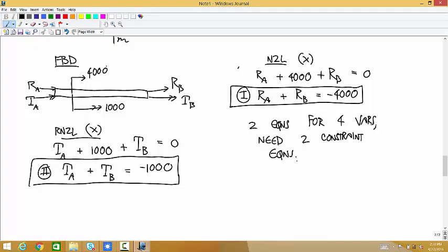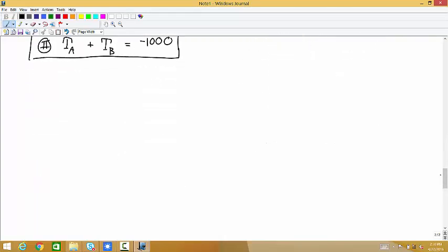Okay, so one of those equations is going to come from requiring that the elongation over the whole length of the beam is equal to 0, because it can't grow at all when it's fixed between the two walls. And then the other one says that the angle of twist, if you go over the whole beam, has to be equal to 0, because neither of those 2 points on the walls can rotate. Okay. So let's do elongation first. We're going to have to do that in 2 different steps, because we have an elongation due to the forces that are applied, and we have an elongation due to the change in temperature.